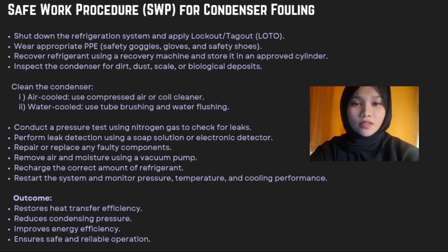The refrigeration system must be shut down and isolated using lockout-tagout procedure. Workers then wear the required PPE before starting maintenance. The condenser is inspected and cleaned to remove dust, scale, or other deposits that reduce heat transfer. After cleaning, pressure testing and leak detection are carried out to ensure the system is safe and leak-free. The system is evacuated, recharged with refrigerant as targeted, and monitored to confirm proper operation. This procedure improves efficiency, reduces equipment failures, and ensures compliance with safety regulations.